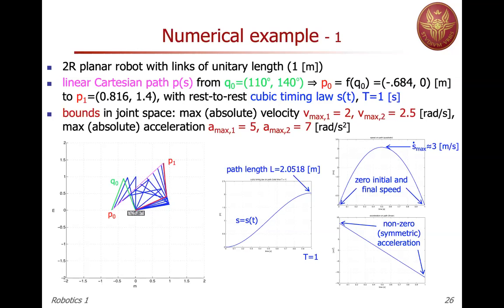We should take this Cartesian motion, and from this Cartesian motion we have the position, and so for each position we do inverse kinematics and we have the associated configuration, and we will always keep one of the two solutions because we start with elbow up. Even the final solution, as you can see, the stroboscopic tracing will be elbow up, although this is reversed, so it seems elbow down, but in fact we never cross the singularity.